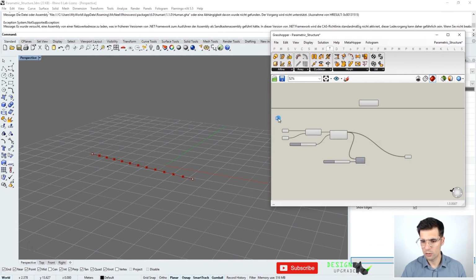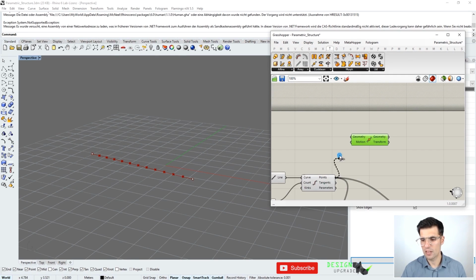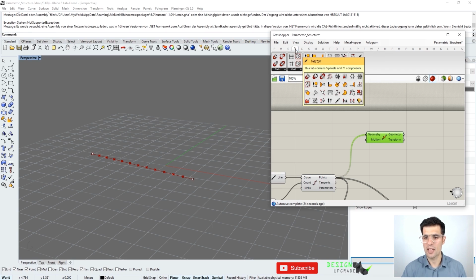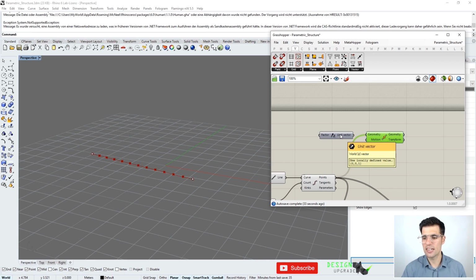So what we are going to do is to connect the points that we created here by dividing our first line with this move component. And now this is the geometry that we are going to move. And now we have to specify the direction in which we are going to move this geometry. So in order to do that, we have to define a vector in this vertical direction. And for that, we can come back to this vector category. And here, we can choose, for instance, the unit Z vector. So this is a vector, if you take a look here, which is just one unit in the vertical direction.